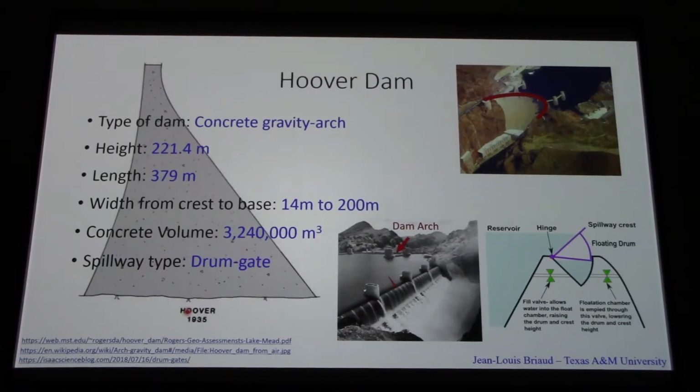So the dam is an arch dam. You can see it here. You know, we have two types of dams. I think I mentioned it before. Arch dams when the valley is narrow and the canyon is pretty deep, and the dam arches and gathers support from either side of the mountain and the canyon.